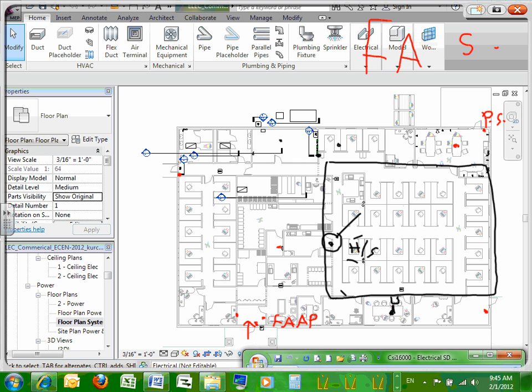Some panels can tell the difference between a smoke detector that's dirty and one that's in alarm. Most newer systems actually can tell what a dirty smoke detector is. And it gets a little more complicated, because some systems are smart enough not to call the fire trucks if it's a dirty smoke detector.